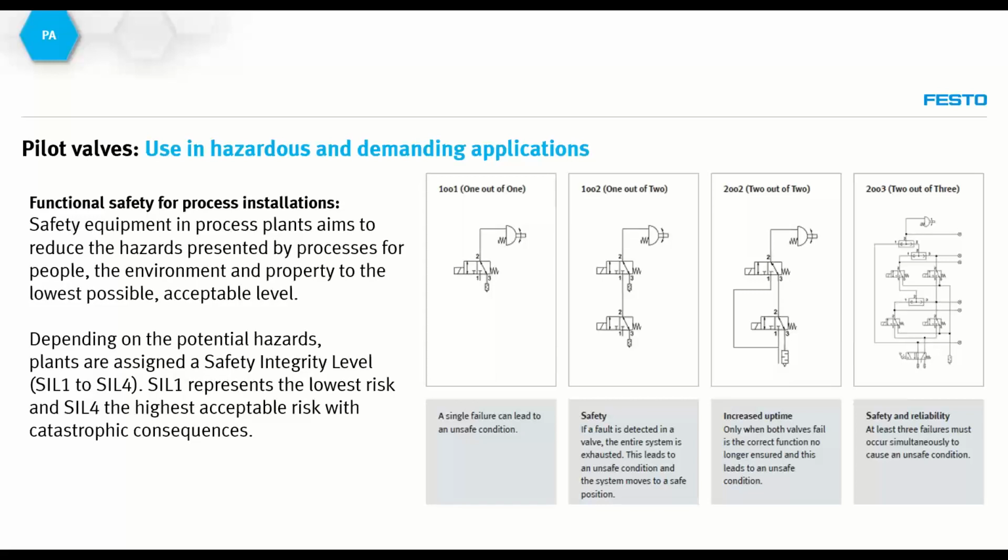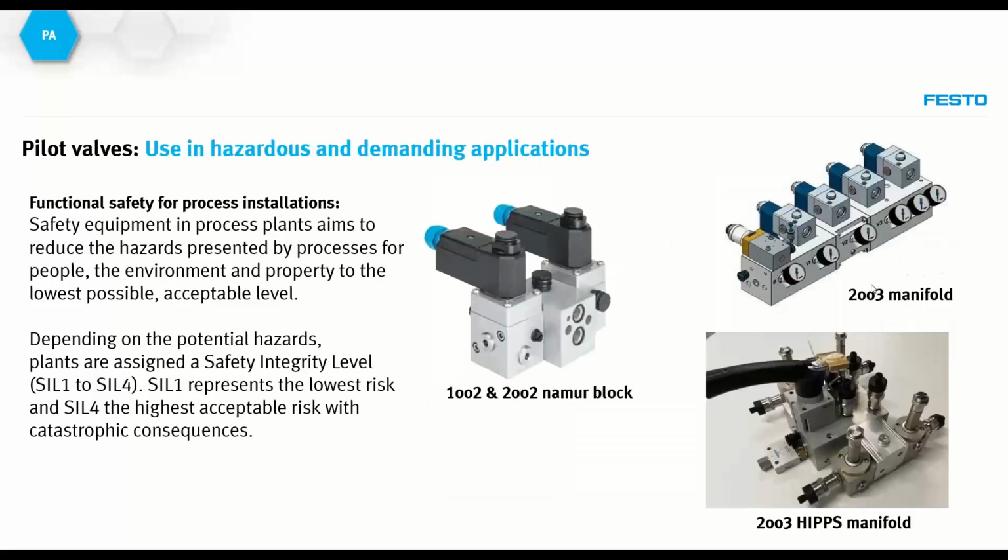An even higher level, and here we are talking more about SIL 3 and SIL 4 applications. SIL stands for safety integrity level. We can even go up to 2 out of 3 designs. Here you see that multiple solenoid valves and logics are being used to operate one single actuator. One of the examples we see in the next slide is how we facilitate this.